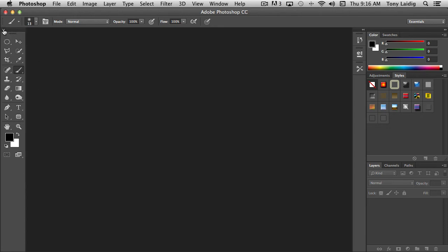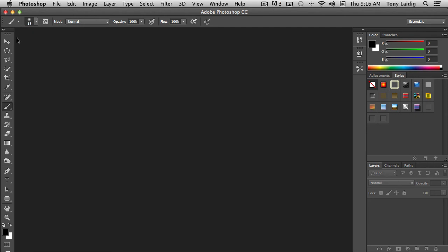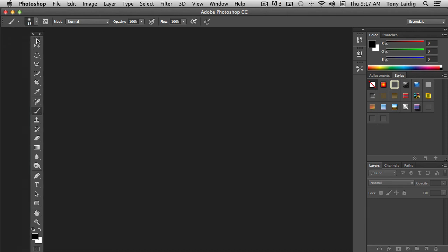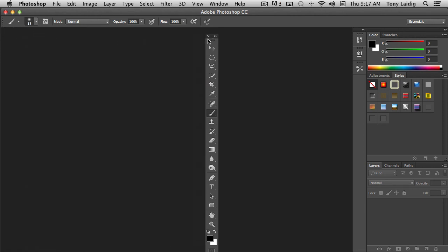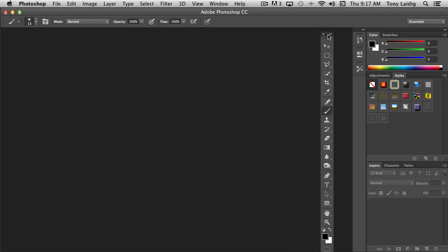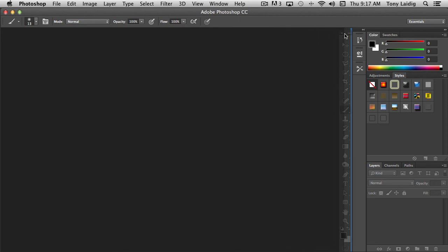Another option that you have with the toolbar, and actually with all of the different workspace bars that are available to you, is that you'll notice that there's a series of dark rectangles here, and if you left mouse click and hold your left mouse key down and drag, it separates the toolbar from the interface so that you can then position it anywhere you like. And as a matter of fact, you can actually drag it over here to the right hand side, and you'll notice how you have the vertical blue line that shows that it wants to dock to the right hand side workspace windows that are there.